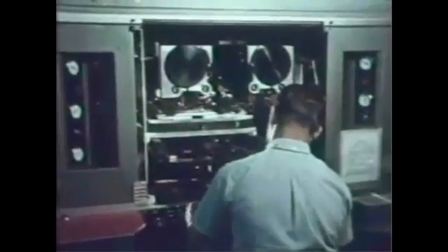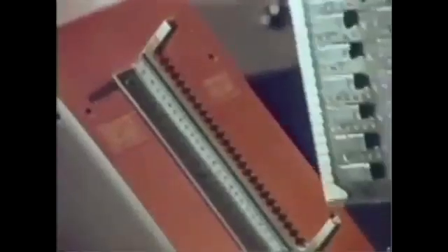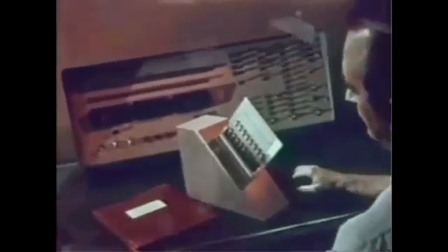In addition, computerized wire wrapping machines are used to make the backplane interconnections so that the inherent reliability of the integrated design isn't compromised. The machine automatically cuts each wire to the correct length, strips the ends, routes the wires, and makes the connections. Meanwhile, each completed circuit board is tested individually. Finally, circuit boards are installed in the computer frame, and the completed system is thoroughly tested.